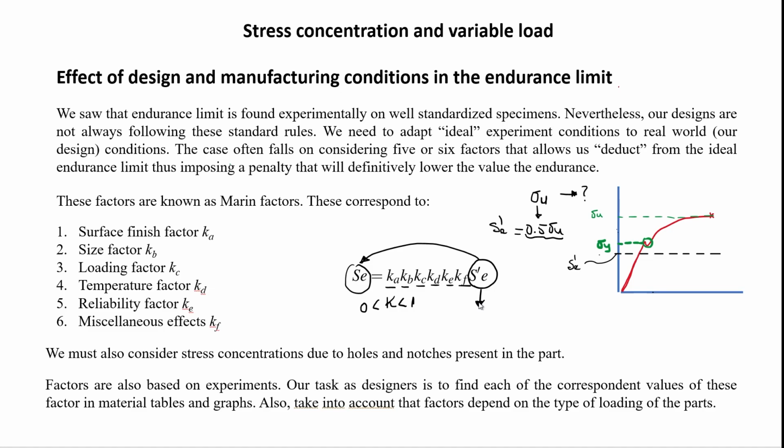So parts that logically would have a diameter D, we're saying no, to compete against fatigue it's not D, it's going to be 3, 4, 5 times D. So imagine how much larger the designs we are devising are going to be, just because of this clear show of fear that we are not taking into consideration many factors because we don't know them. And then we say, okay, let's take a look at those factors.